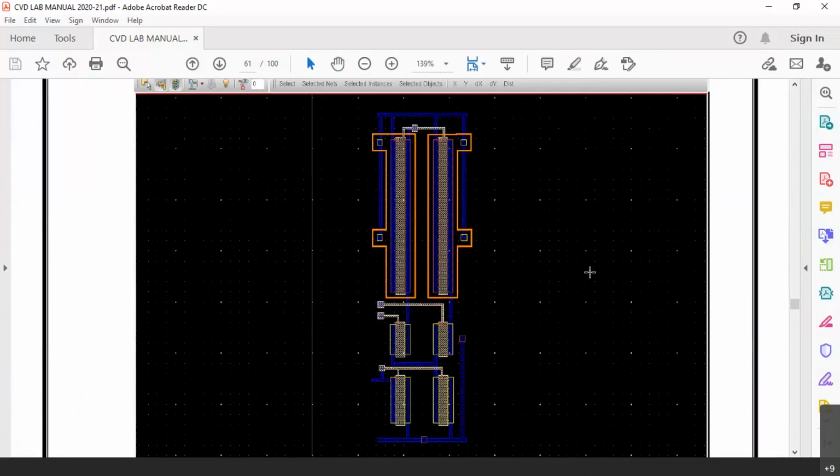That means the simulation or the verification of the layout by giving the input signals to the same. Now there are parasitics in the layout. Along with the parasitics, now the performance will be slightly degraded. But we will have to compromise with the degraded performance only now, because this is the one that is going to be manufactured in the foundry.